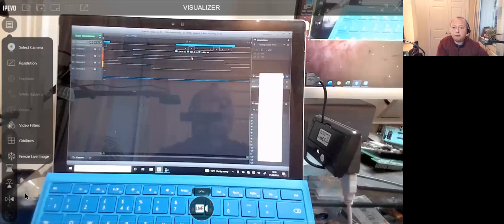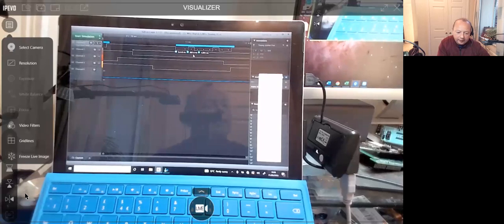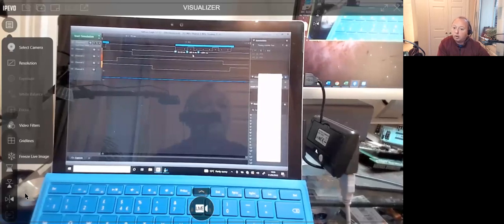and you're maybe sending the wrong AT command, and your module's not working, this will very easily tell you what data you're sending. And then you can see exactly that. Maybe you're sending the wrong command. Or I was working on a project many years ago now, we were using this, and the customer reported they didn't have a SPI running properly. So we just connected this up, and it was very obvious that the clock on the SPI wasn't running properly.